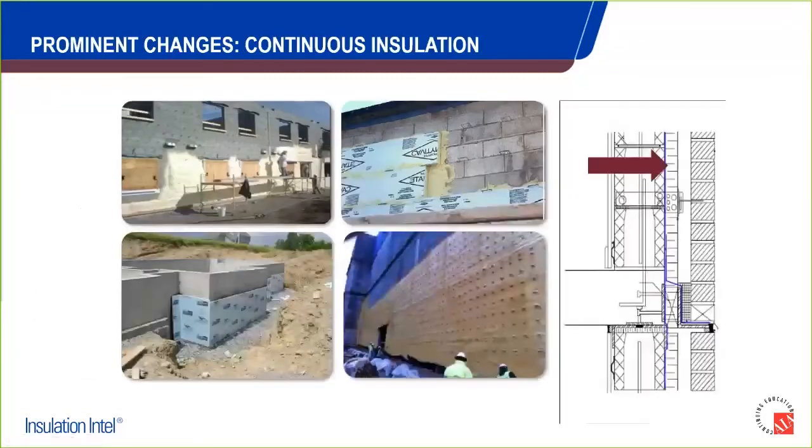So we're getting towards the end here. Let's look at some things that are driving the requirement for more testing, and that's primarily this requirement for exterior insulation. Again, it was noted some 60 years ago that this was a very effective way to insulate a building, adding exterior insulation, which basically covers all the bridging elements, the thermal bridging elements of the structure, and insulates those. But at the same time, it has brought other combustible elements into non-combustible assemblies.